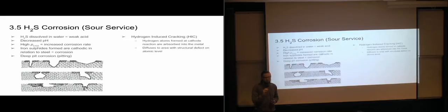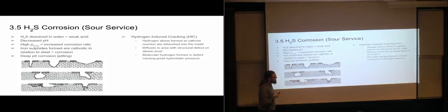But if they do find a structural defect, somewhere in the crystal structure where there is a defect or maybe a very tiny crack or something like that, then these hydrogen atoms are going to gather there. And then we get hydrogen molecules instead of hydrogen atoms.